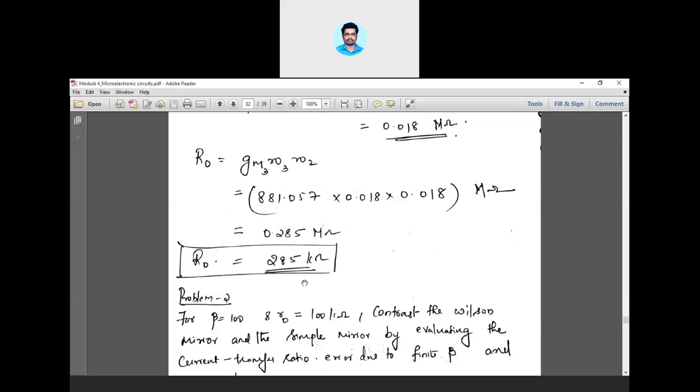the drain terminal. So you have an equation V0 which is equal to Vt plus 2 VOV. So first of all, you have to find VOV. VOV can be found by using the typical output current equation. So once you find the value of VOV, substitute in the equation Vt plus 2 VOV, that will get you the value of the output minimum voltage.